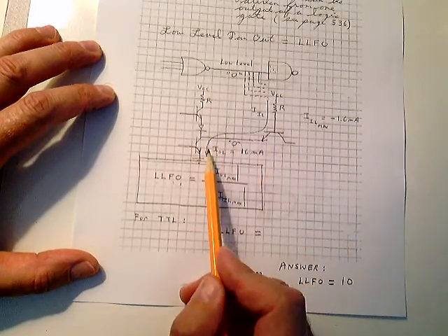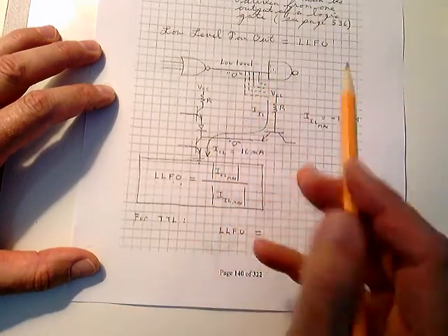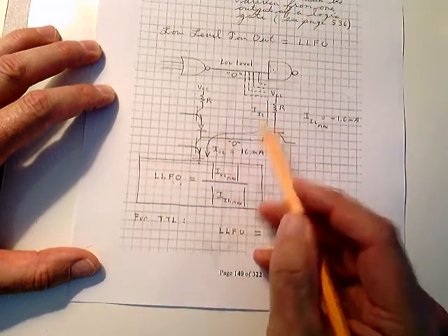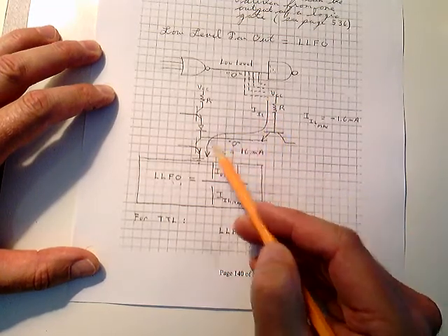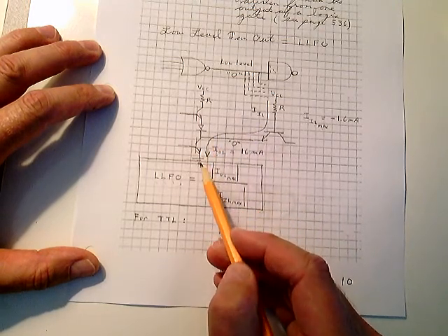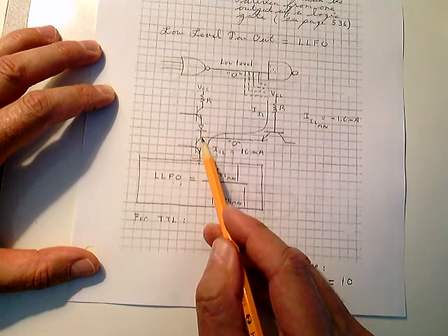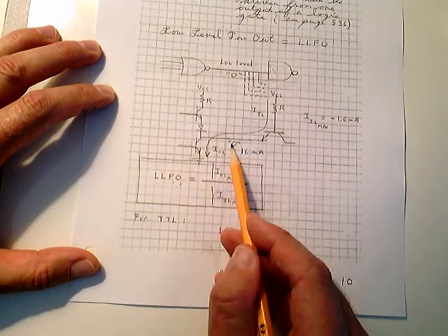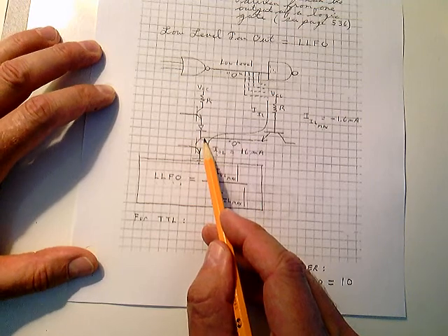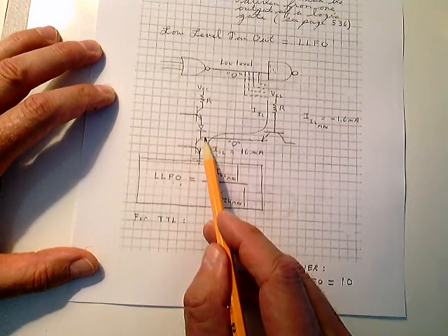But the problem is if you tie another input on, and another input, you have more current coming back this way. If you go to 11 or 12, you have more current. And for every bit of current you push down through this output, this transistor really looks like a resistance here. You're building up this voltage. In the low state, this voltage, they're no longer going to guarantee 0.4 volts. It'll go to 0.5 volts. It'll go to 0.6 volts.